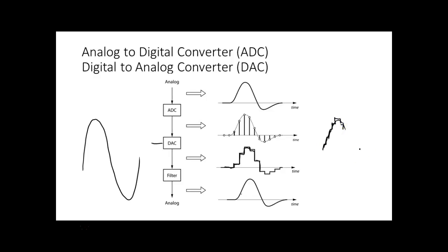Or we can filter it. We can run this through filters like inductors, and we can take a crummy digital output and turn it into a pretty nice analog signal, like variable speed controls for AC motors, variable frequency control. These guys output a real choppy signal, but they filter it before it actually hits the motor. Some of them do.